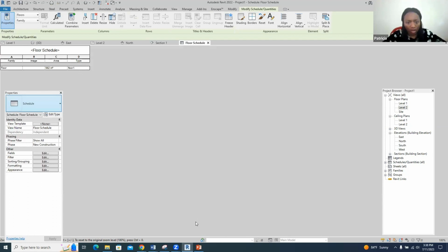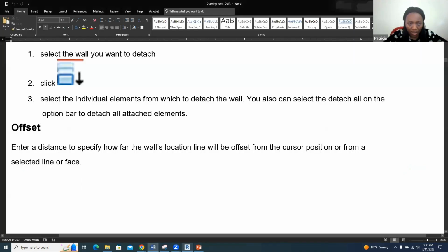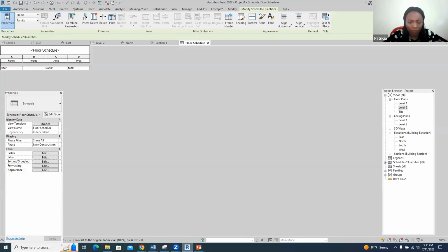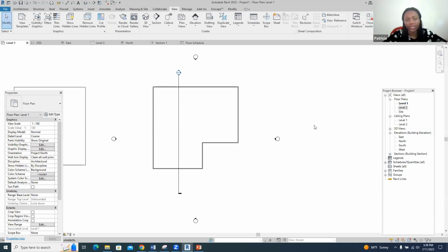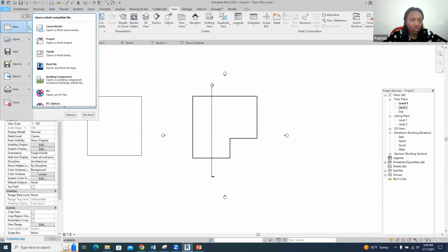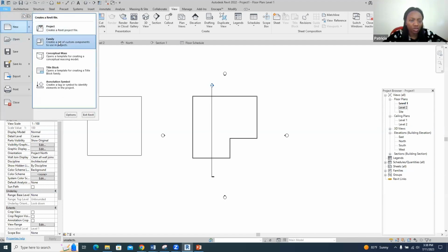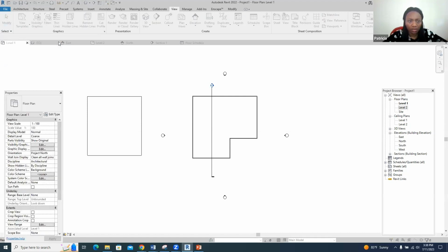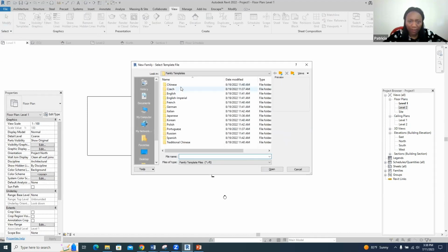Wow. Okay, so you mentioned something again, the doors and the windows. So in part of the titles, the thing that we'll do today, we talk about how do you create your own door and window, okay? So we had what we call the families. So if you go to this file, and then you say new, instead of a new project, it will be a new family. So when we come to new family, we have different countries, like the languages, simple that always just go to English.